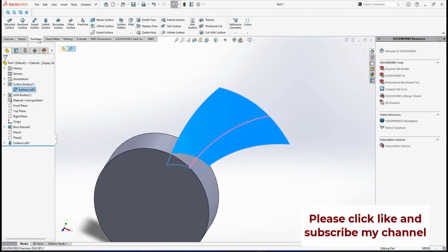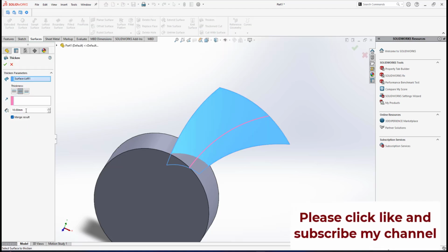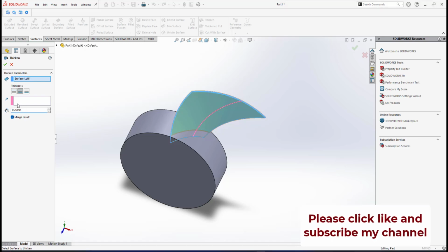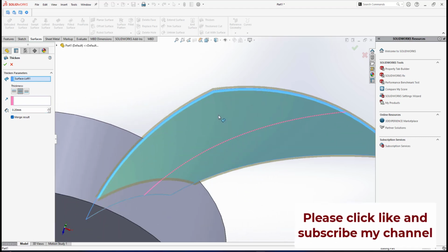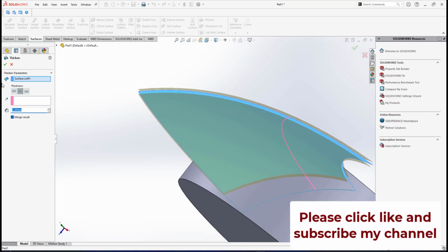Okay, under the surface menu here, when you have a surface, you can give it a thickness to make it a solid. So under the surface menu, we go for thicken. So thicken. Because the fan blade is so thin, for the thicken value I put 0.2. So it means that it is very thin, right? If I go for 0.1, I think it's too thin. Let me go for 0.1.